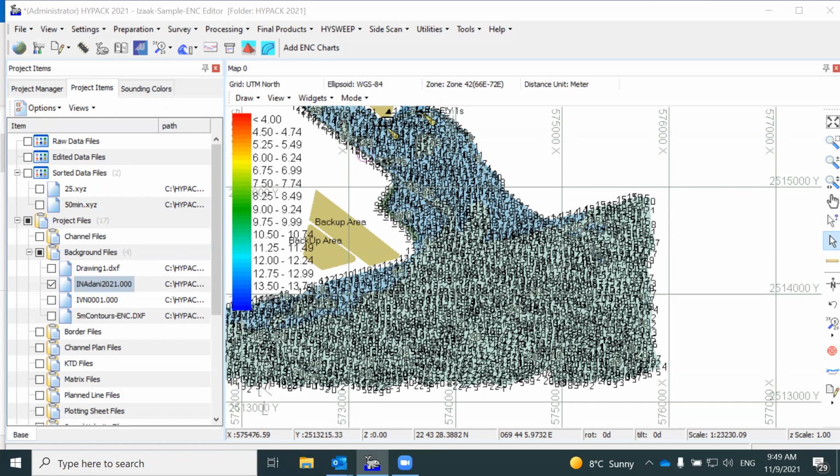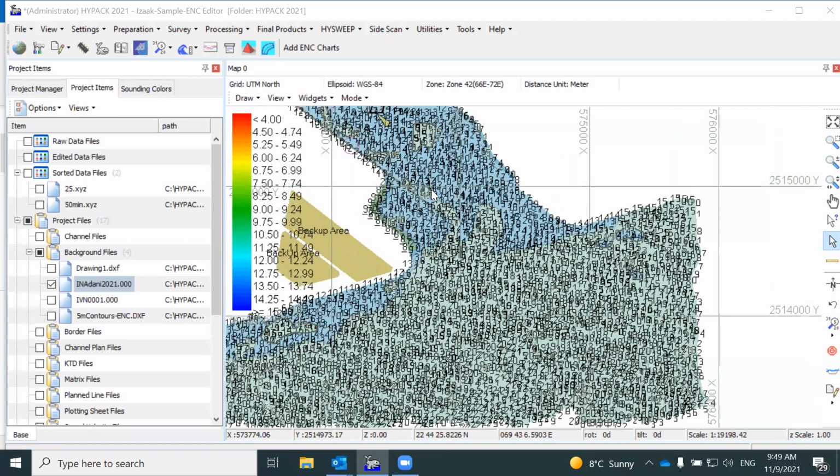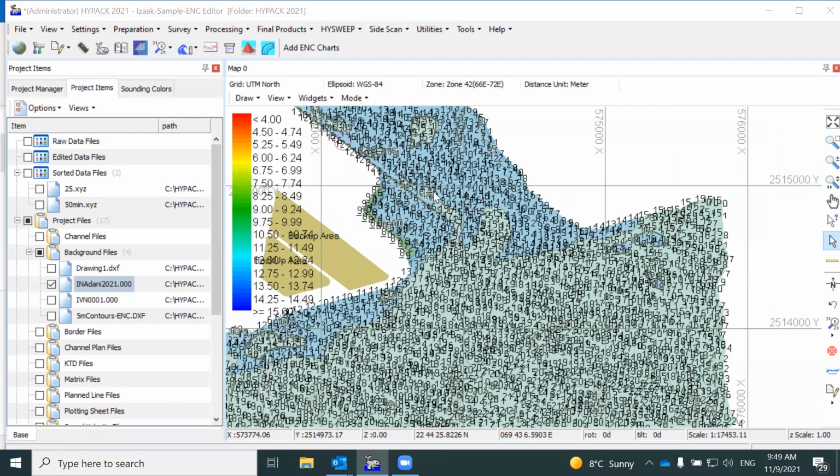That's a good question. Mr. Arvind Gupta is asking if soundings will be in black color. Yes, in any ENC, you will see soundings not colored. They are all the same black color. Well, it can be grayish, as I said. You can set this shallow depth so that the deeper depths would be grayish, but yeah, it's not colored. ENC chart doesn't have this red, all this color table. It's not applicable for ENC, though there is an option. Let me show you that option here. So it should be black. It's a rule.